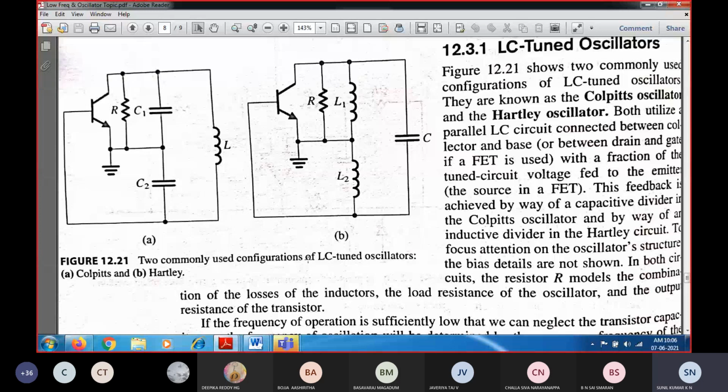In order to find the gain, we have drawn the corresponding AC equivalent circuit of the RC phase shift oscillator, and we have obtained the gain of the amplifier, and also found what the feedback gain should be. Since the feedback network comprises only passive components, it not only provides a 180 degree phase shift, but the amplitude of the output signal of the feedback network will be reduced with respect to its input.